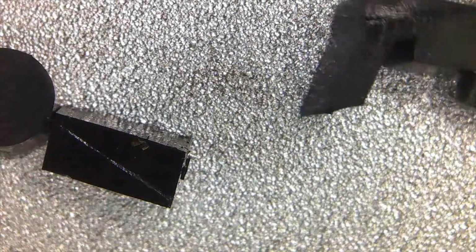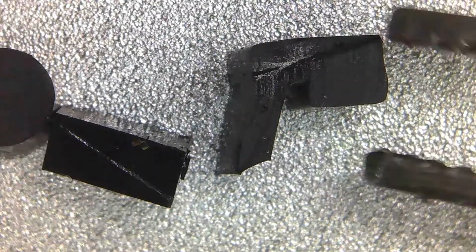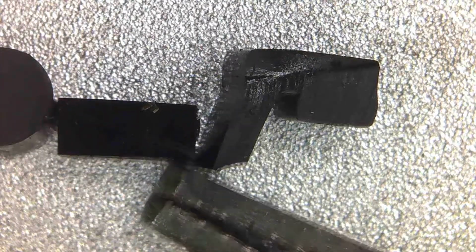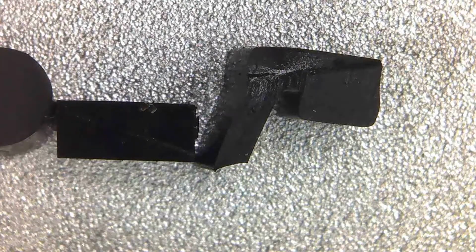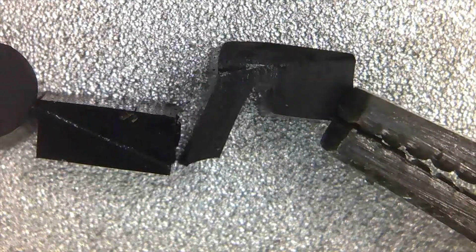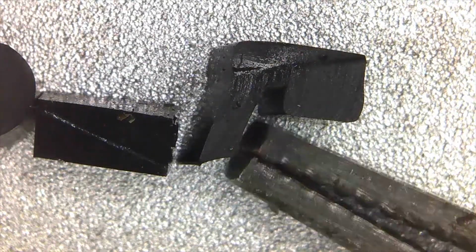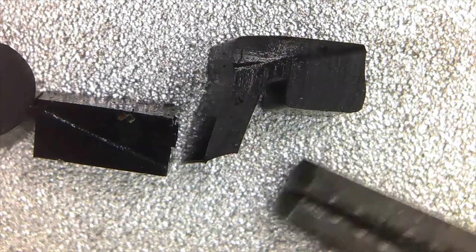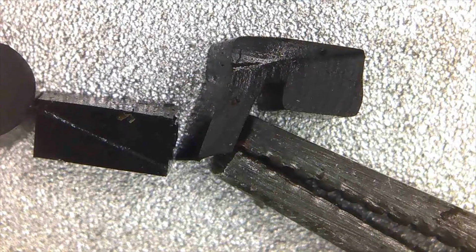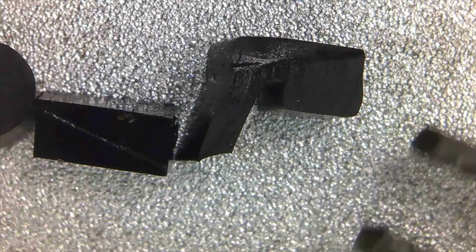Then the last one here that I have is the lip seal. Now this is a much more dynamic seal because it doesn't require so much external static pressure, meaning whenever this piston was in the bore, say with the square cut seal or the O-ring seal, there's a lot more pressure against the wall of the bore to seal the piston. With this one here, the lip seal, we can see because it's got that shape to it, this undercut, and then of course the lip right here, hydraulic pressure happens on this side, and what happens is it causes it to push out and seal better against the wall.